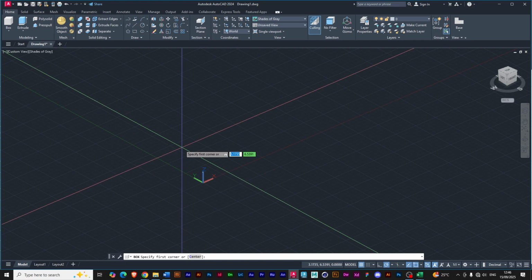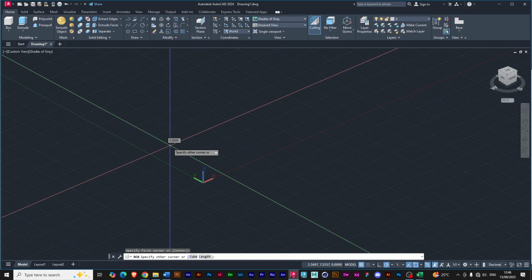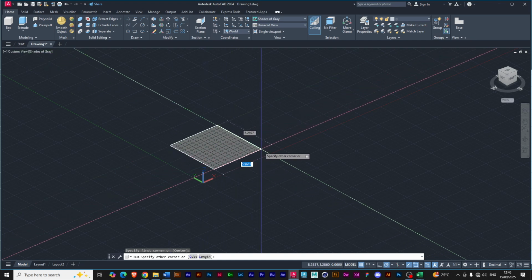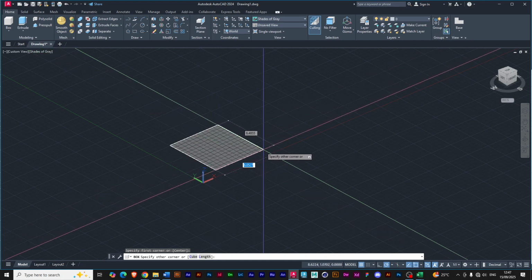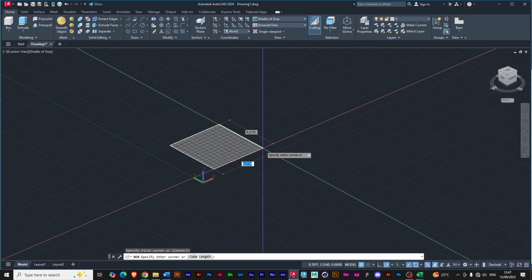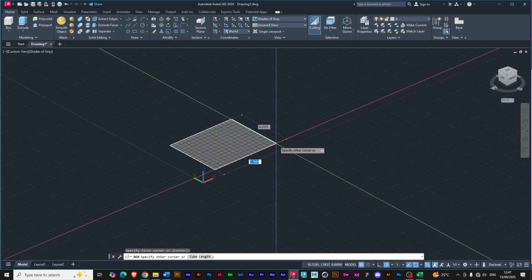Let me draw a normal box first. So I'll just click anywhere. Click first to activate the first point, and then don't click and drag. Just click. Click anywhere, yes. Once your mouse moves away, it is going to be trying to detect the size, the width or length of the box. So specify the other corner by clicking wherever you feel you want the box to stop.